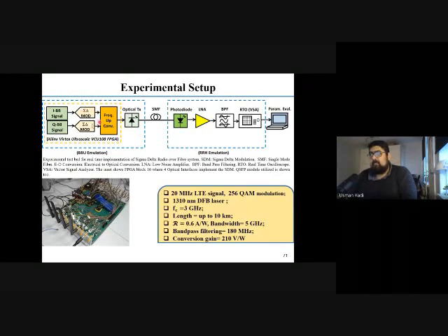So we have Sigma Delta modulation and we have frequency up conversion. And then again, we have the laser, we have fiber, and we have photodiode. So the 1 bit ADC, the frequency up conversion, the creation of this I and Q was done on a Xilinx Virtex VCU108 FPGA board, a very sophisticated board.